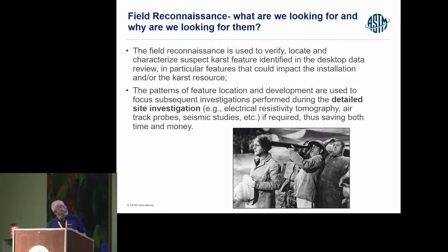So the field reconnaissance, what are we looking for? We're looking to verify and locate these suspect karst features, and the pattern of the features' location is used to focus a subsequent investigation if necessary. And generally, like I said, we have this preliminary investigation and then a detailed investigation with the second phase.